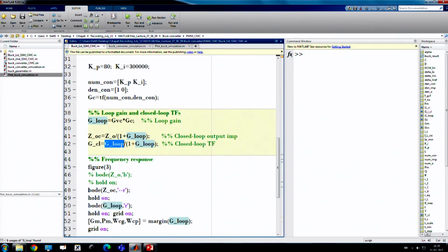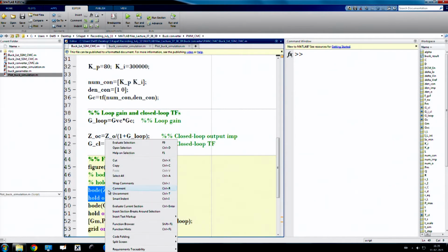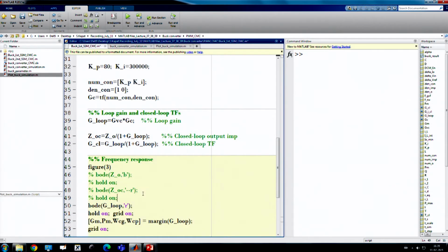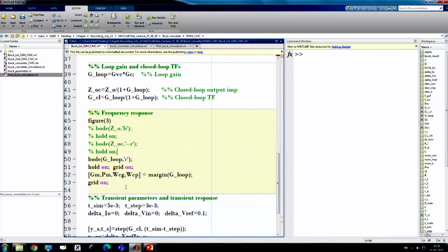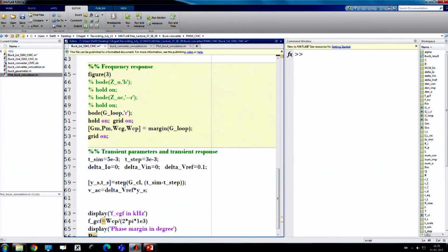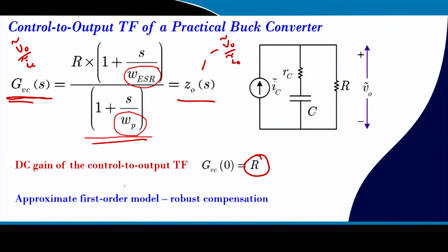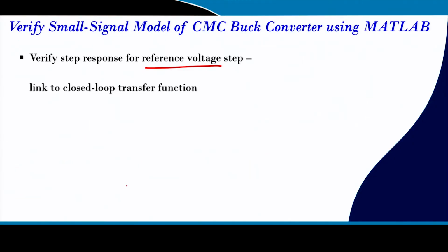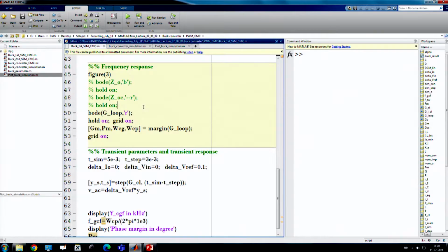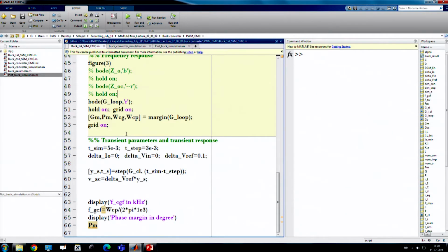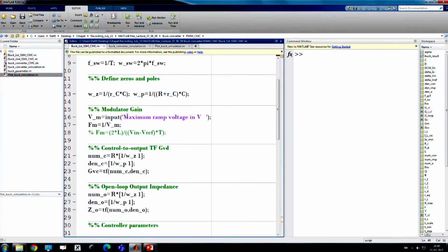And here we have all the Bode plots. So, once we have the loop transfer function, we can find out the gain margin, phase margin, bandwidth and crossover frequency and all. So, initially we want to carry out a reference voltage transient, because what is our initial target? Reference voltage transient. This will give us the bandwidth concept, okay. Then we want to match the model, okay.